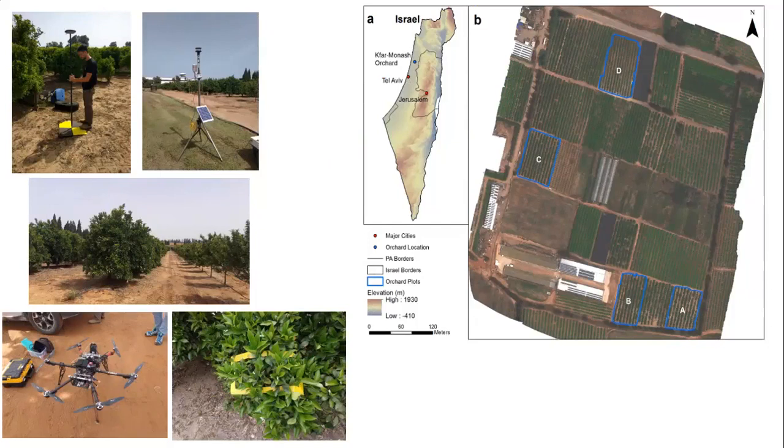On the specific drone, we have several cameras: a thermal camera, a multispectral camera, and a high-resolution RGB camera. And we're developing a special scale model based on field sampling of the leaves and nutrients, and developing a machine learning application for predicting nitrogen levels.